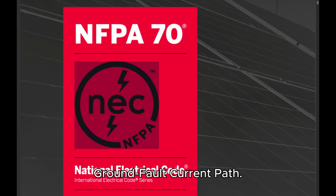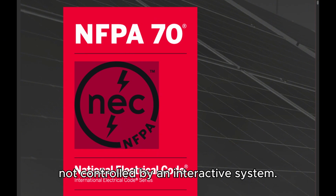CMP2 effective ground-fault current path. An intentionally constructed, low-impedance electrically conductive path designed and intended to carry current under ground-fault conditions from the point of a ground fault on a wiring system to the electrical supply source, and that facilitates the operation of the overcurrent protective device or ground-fault detectors. CMP5 electric power production and distribution network. Power production, distribution, and utilization equipment and facilities, such as electric utility systems that deliver electric power to the connected loads that are external to and not controlled by an interactive system.